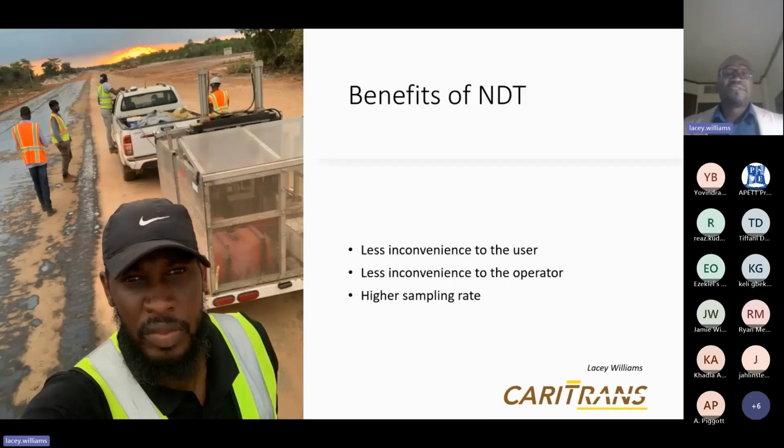Well, with the equipment that you see in the background there, an FWD, we were actually able to, in a 6-hour period, undertake 46 kilometers of testing at a particular interval. But if you were to just use the example of a test pit every kilometer, and do one sample every kilometer with this piece of equipment, then in no time at all you would be able to complete your testing and get a, not an accurate, but a fairly reasonable estimation as to what the condition of the road structure would be.